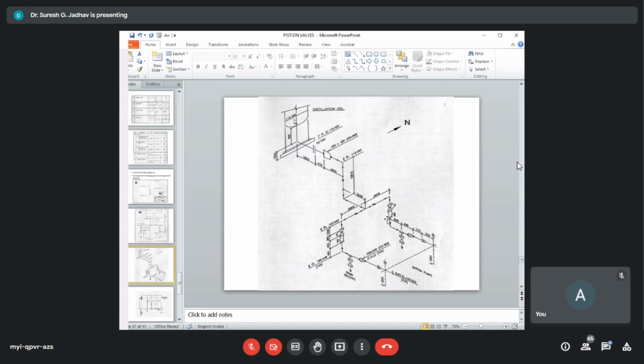Now next point is the equipment layout is reproduced on the piping GA to its scale and drawn on the reverse side in case of manual drafting. In case of CAD, a separate layer is used. The major primary beams and secondary beams are also shown if the area covered is indoor.